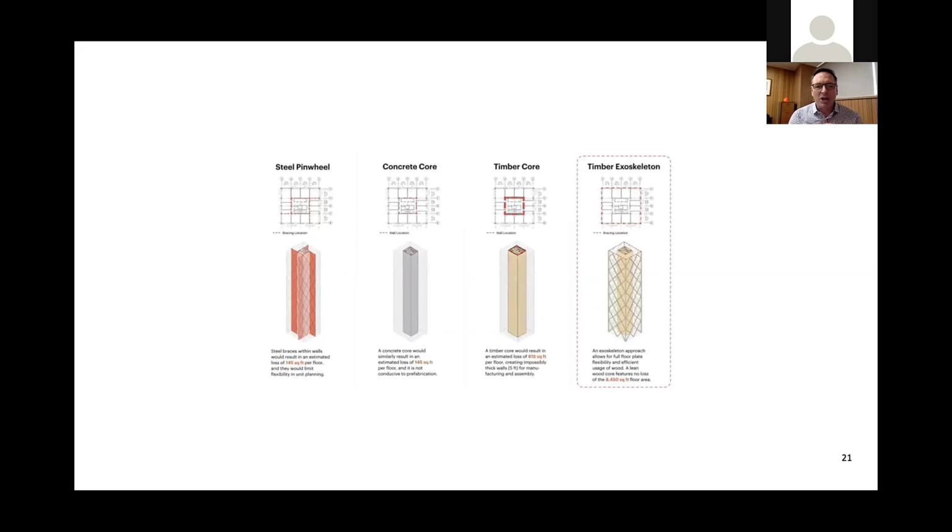If you're looking at the structure itself, there's several concepts here. So this is the PMX system that was developed with Michael Green. Sidewalk Labs is the proponent of this particular system. So you'll see here a steel pinwheel, you've got a concrete core, you've got a timber core, and you've got a timber exoskeleton. The timber exoskeleton has become the one that's most prominent in use at the moment, and we've got an example of that coming up. But in essence here we're saying that where you might have steel or concrete, you can equally build with timber, and the exoskeleton approach seems to be the one that's got the most weight at the moment.